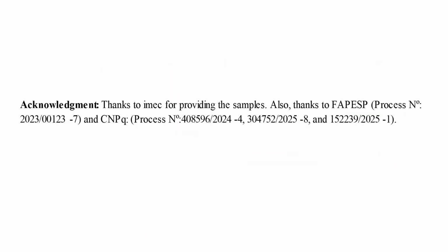Conclusion. This work demonstrates that the VTH extraction method critically affects the interpretation of geometry-dependent behavior in high-mobility electron field effect transistors. Linear extrapolation provides the most consistent VTH definition, enabling dependable VGT normalization, and avoiding misleading geometry-dependent interpretations that may arise from inconsistent VTH extraction methods.